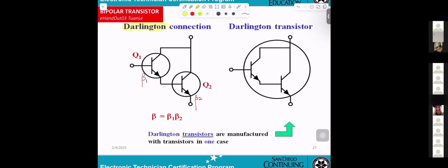However, if you want to design an amplifier to make your voice louder, then it has to be in the active region. So basically the transistor can be used either for switching or as an amplifier.